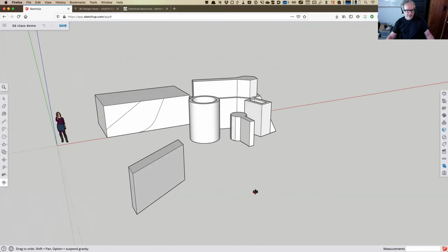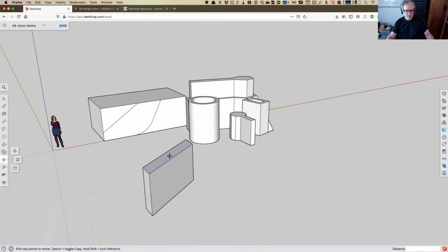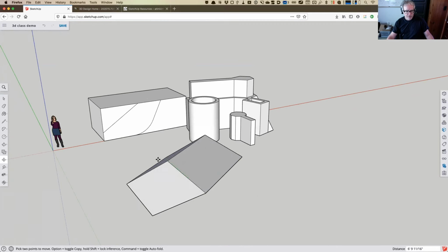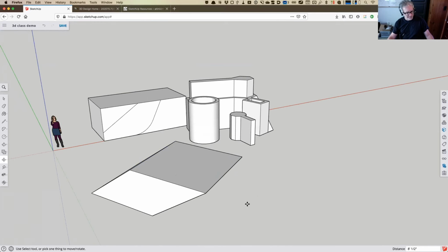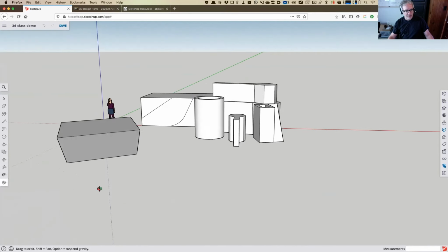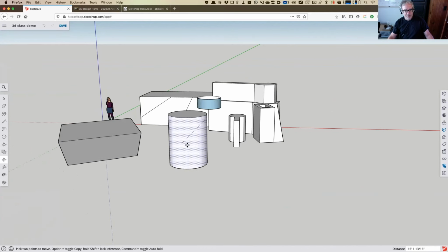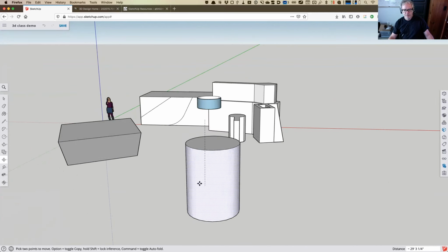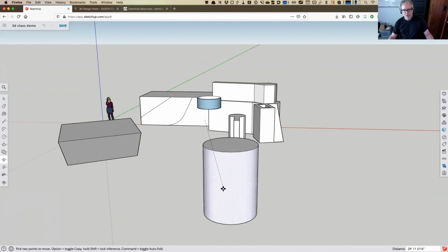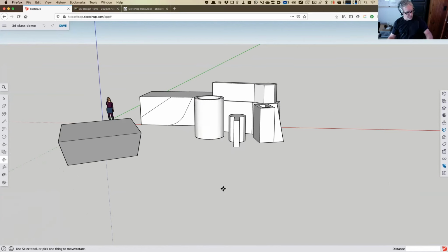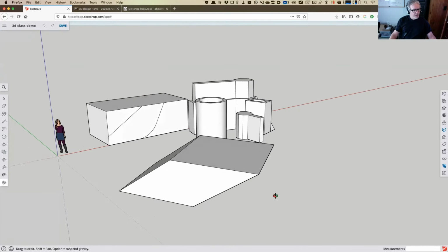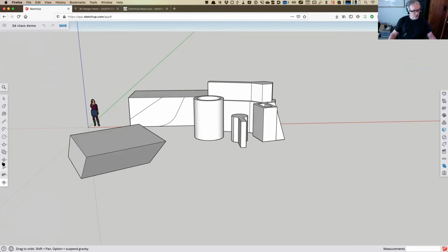Okay, so I can take a plane and I can move a plane separately. So now I can really get some interesting stuff. All right. So I can grab single planes and move them. Now notice again, this does not work on something like the exterior surface of the cylinder. It'll just grab the whole cylinder, because it doesn't know how to stretch the cylinder around. So that works not only on planes, but works on lines and points too.